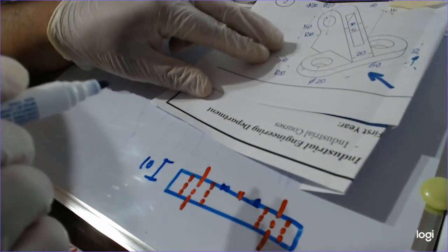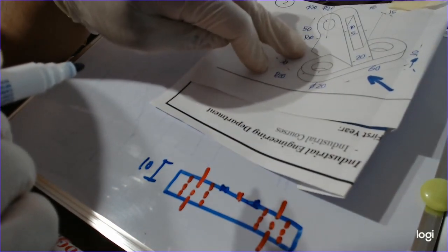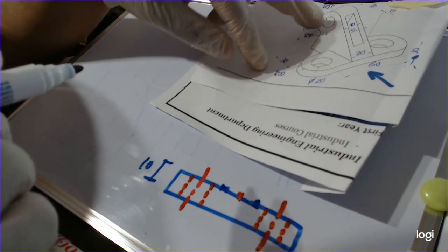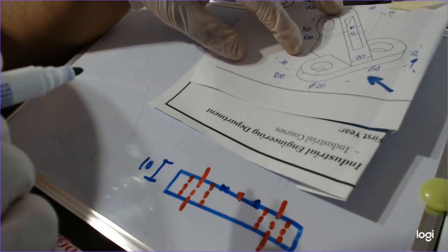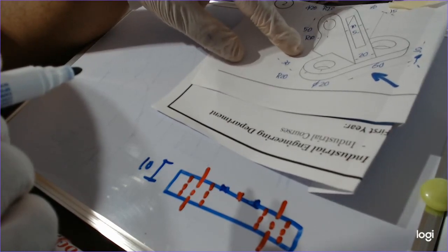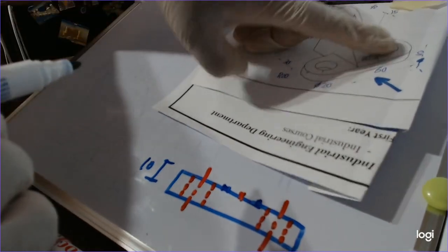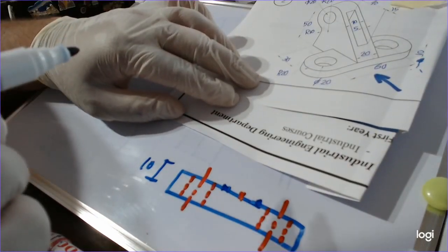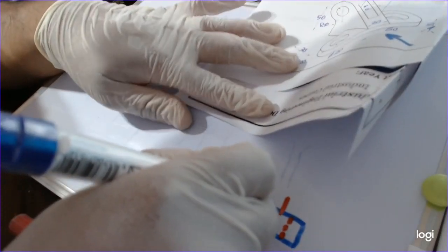And it says here the distance from the peak down point is 50 to the center line of this cylinder, and we have 20 millimeters, so the overall distance to the peak will be 70, 50 plus 20, and we have to subtract this 10 millimeters, so we'll go up with 60 millimeters. Okay, so I will go up 60 millimeters.